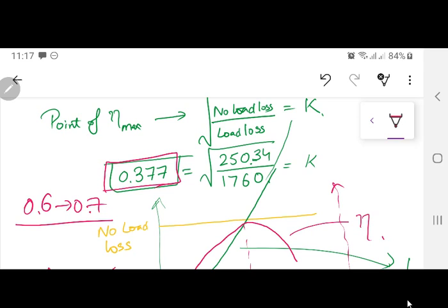The reason is very simple. In the morning time we have all the classes on, everything, so we can turn on all 3 generators or maybe 2 generators depending upon our AC load. But in the evening time, no classes are happening, only the colony or maybe just a few MSc classes are going on. So maybe we can just run a very small plant over there. In this way you can actually run your generators or plants at the maximum efficiency.